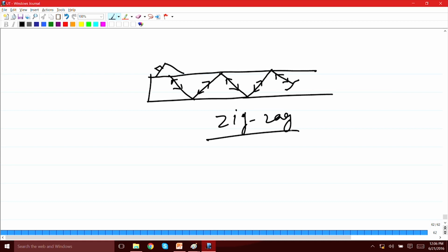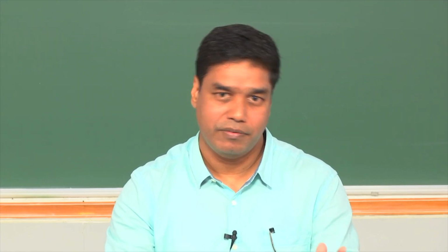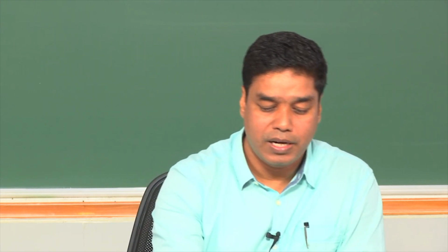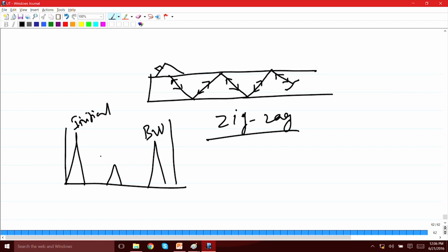Okay. So, that means in this case, as I said, you do not have the back wall which we have used in case of normal probe as the reference. Okay. So, if you remember, our reference was always this back wall signal. This was the initial pulse and this was the back wall. And we use this back wall as the reference, and we said that anything coming before the back wall like this is a defect. Okay.